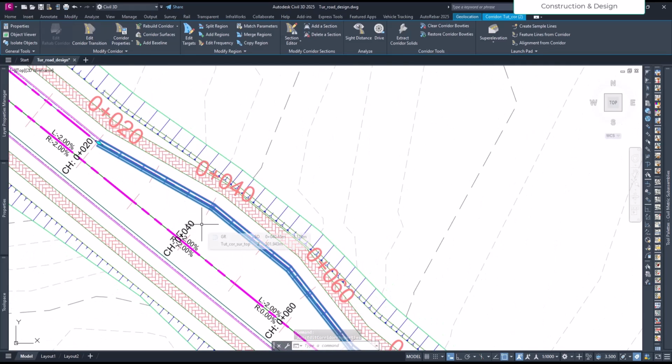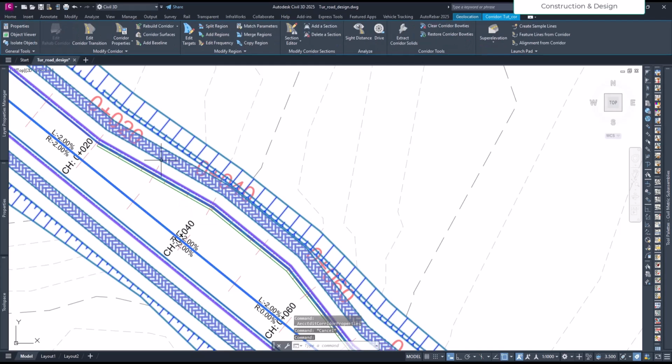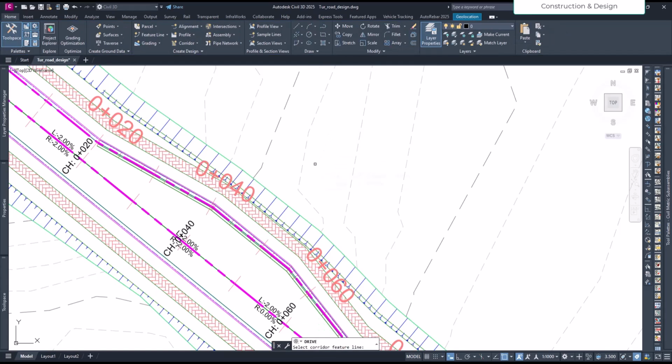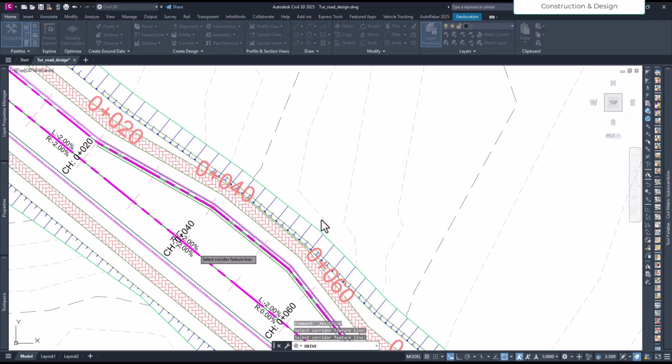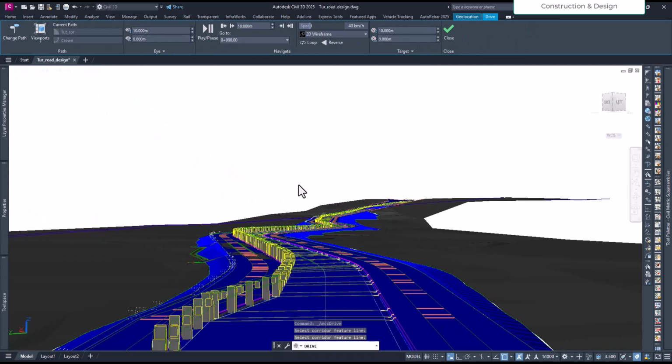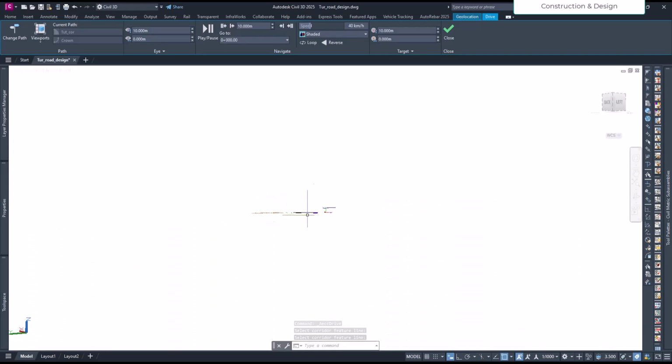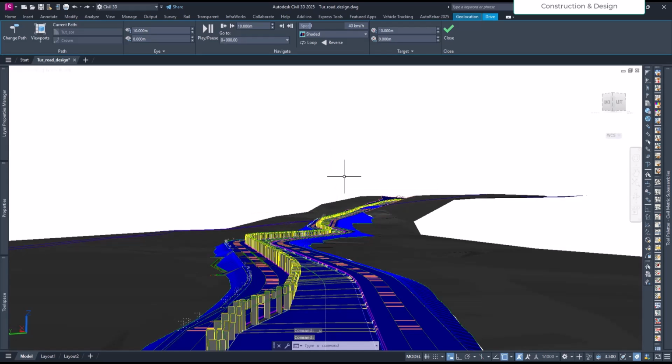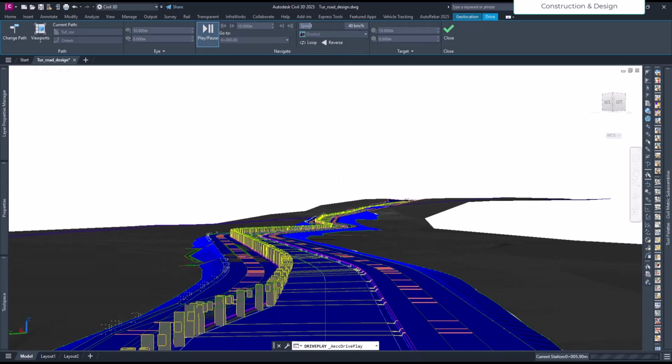And let's go in the dry mode again. Just click our corridor and enter the dry mode. Select the corridor feature it is saying. So I will just select the alignment, ground, and say OK, and just wait. Now you see this guardrail appears properly here. Sorry, I clicked on something. Control Z. Okay, we reset this view, and we can see the guardrails.